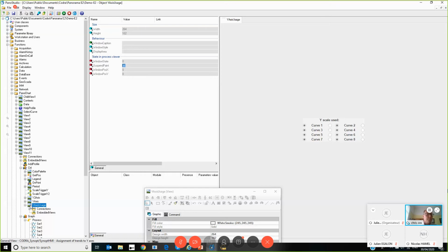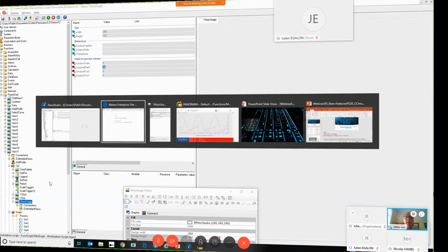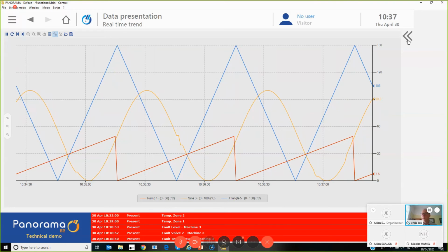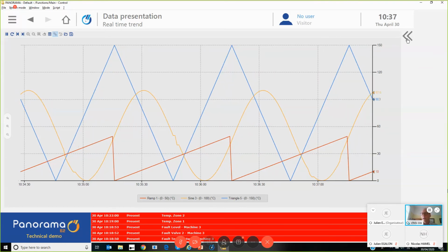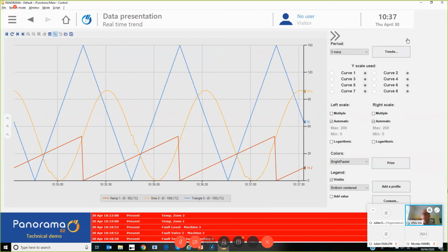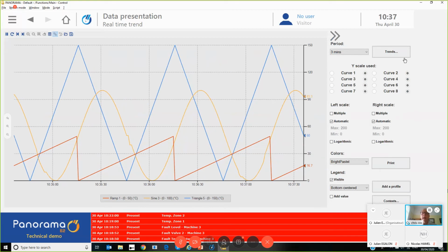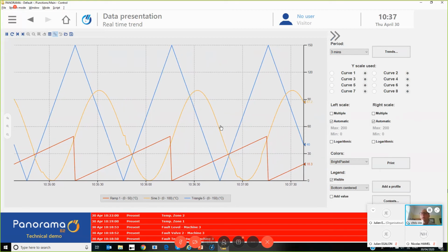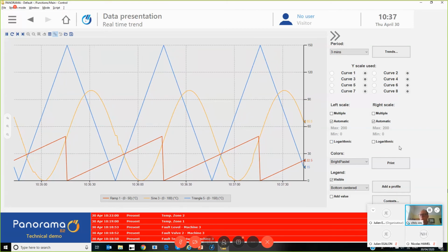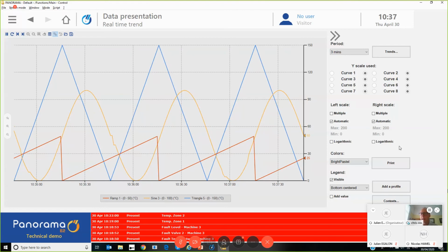And in fact, hopefully when I change screens this time, you will still follow me. Okay, with this screen, we've got some graphics positioned just off screen. And we've got a little button here, which is not an HMI object. It's just a dynamic object in the screen, which will pull that graphic and reposition it, and will rescale the rest of the screen. So you can now see we've got some controls here that we've given as an operator control panel, just using bits that we've got from the HMI object.